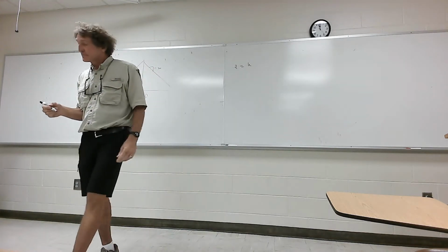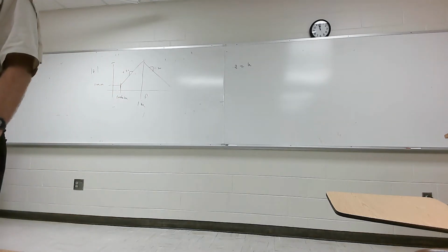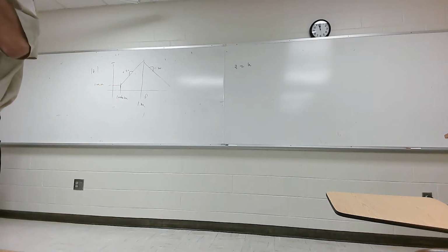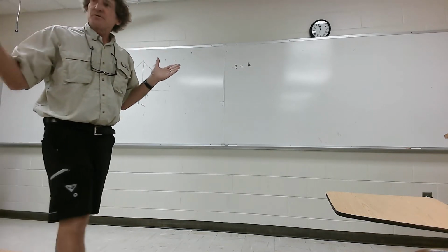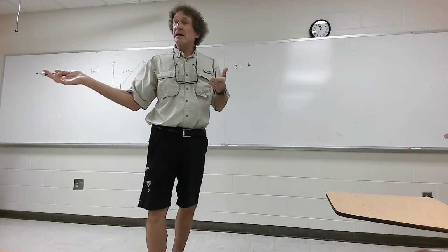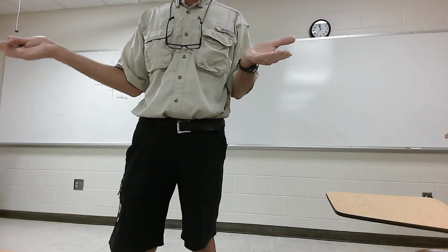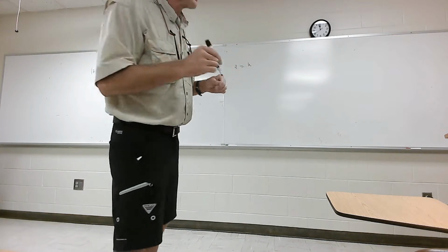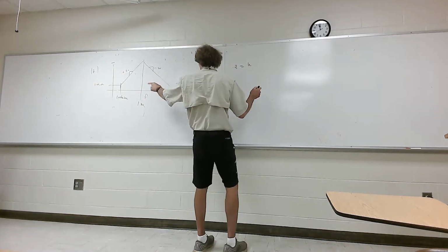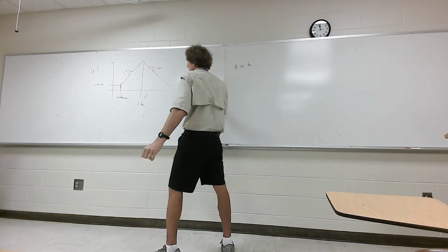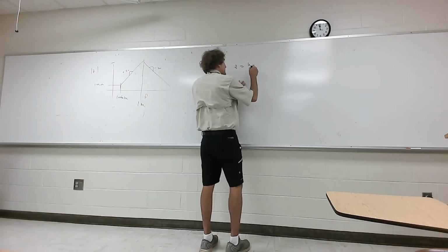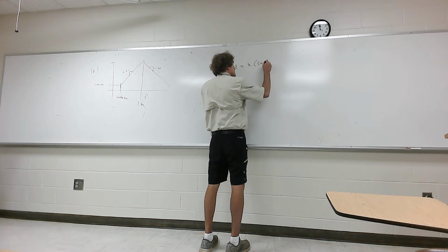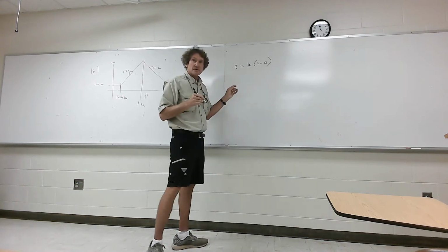There is another plot right beneath it. Yeah, it's a phase plot. The phase is going to flip, it's going to go from plus 90 to minus 90 at the resonance. It just tells you if it's plus 90, it's an inductive reactance, if it's minus 90, it's a capacitive reactance that dominates. That's the only thing that phase plot does. Then I take a look at this, and it comes in at 100 kilohertz. So that means I have s plus some a, that's going to be the lower frequency there where it comes in.